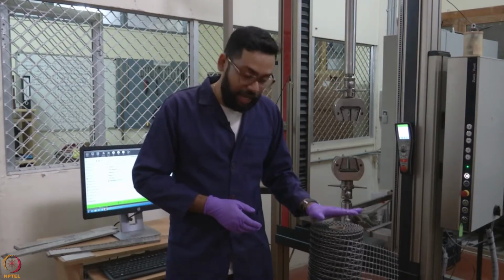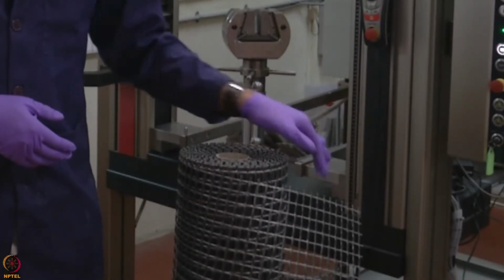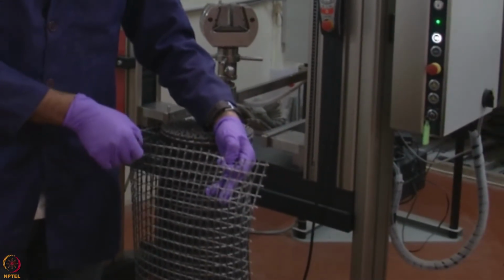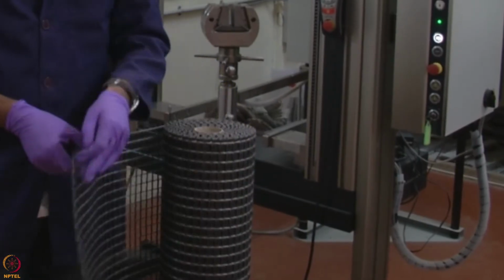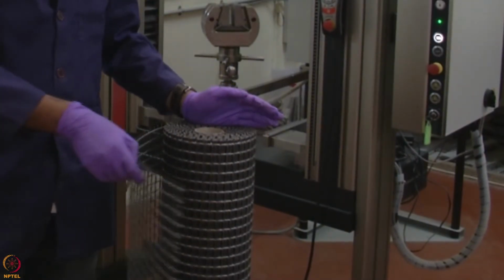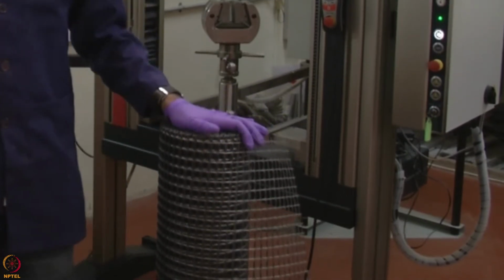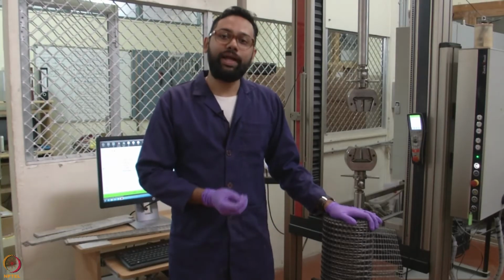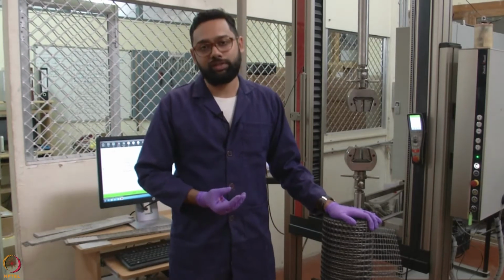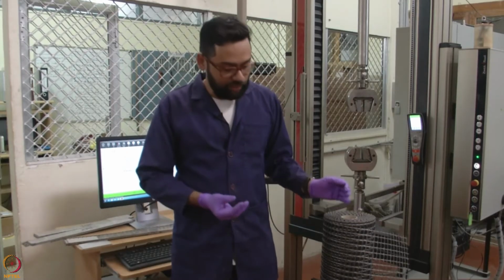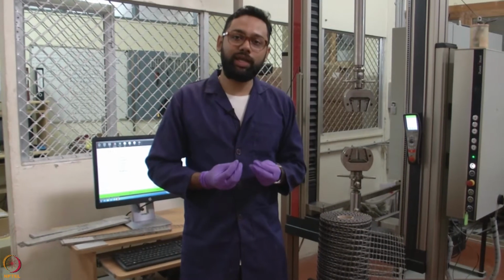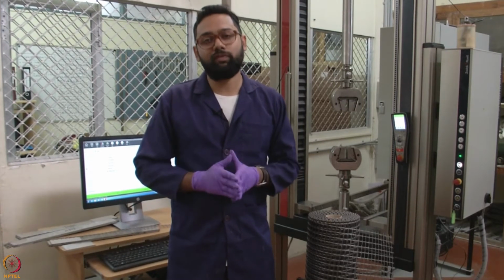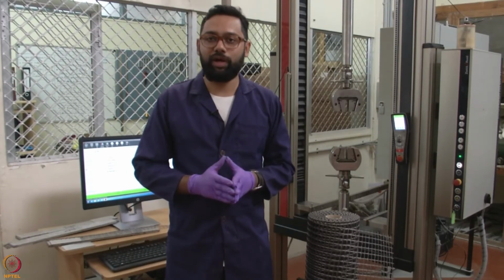Here with me I have an example of what a textile is. This is glass fiber textile, coated E-glass textile. These textiles come in a roll of 50 meters, usually with a width of 1 meter. We incorporate this in fine grain concrete because when you have textiles with small meshes, you need very small aggregates such that they can easily penetrate through the small gaps of the textiles. That is why we use a fine grain concrete.